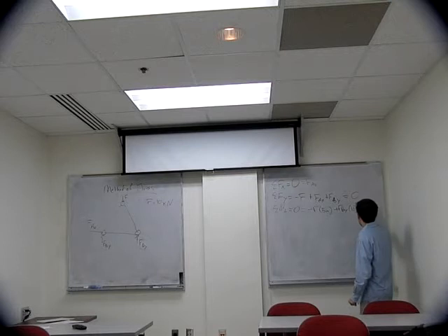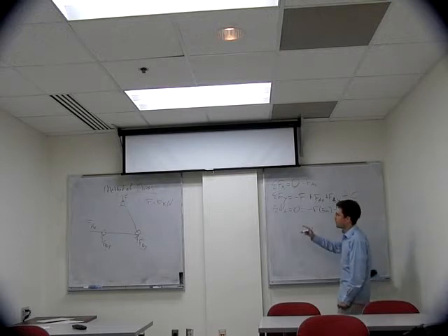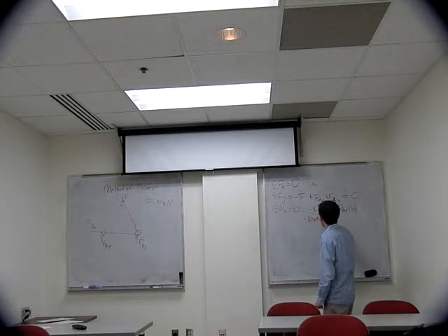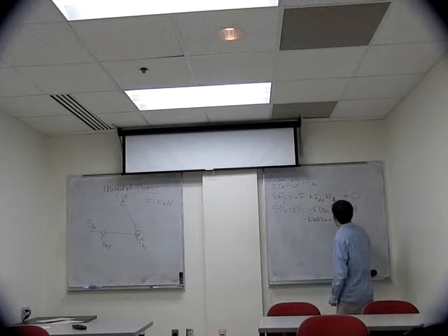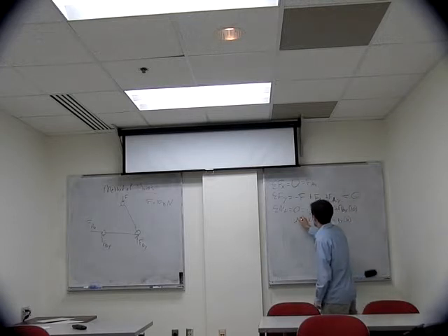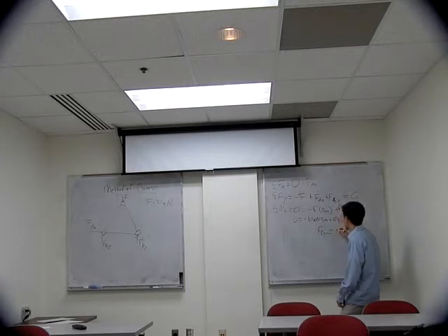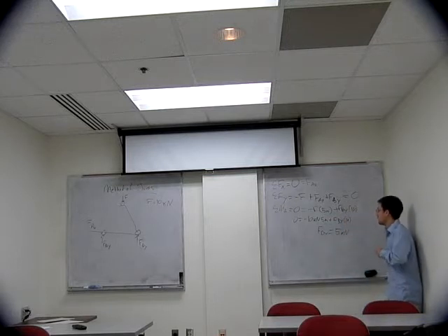And this is going to be equal to 0. We know that our applied force is 10 kilonewtons, times 5 meters, plus FBY times 10 meters. So you can see here that FBY, our reaction force in the y direction at B, is going to be equal to 5 kilonewtons. All right? Any questions on how we got there?